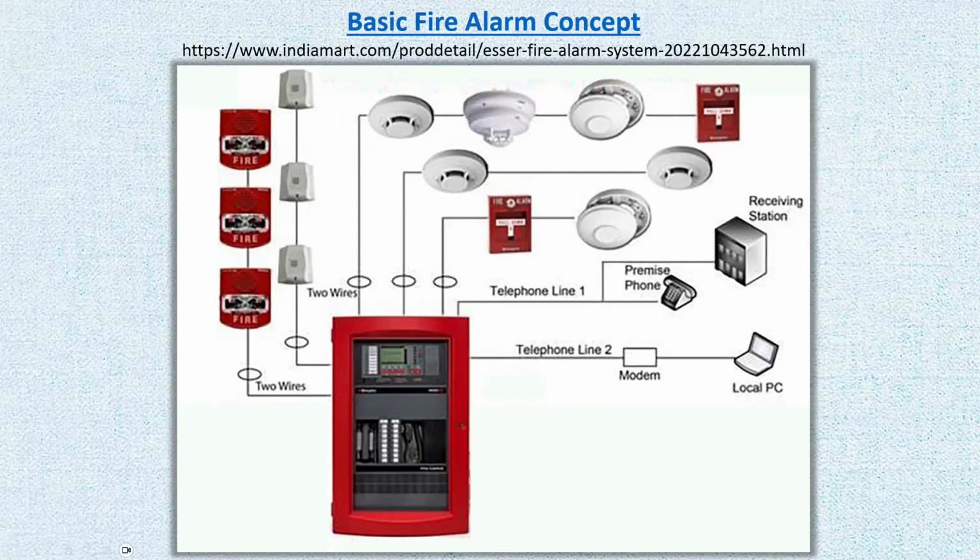All right. So in that panel here, we also see the annunciators, and there are rules and regulations as to a certain noise level, a certain power level for the noise to be made by the annunciator when the fire alarm goes off or triggers into a fire condition. And then, of course, there are strobe lights.